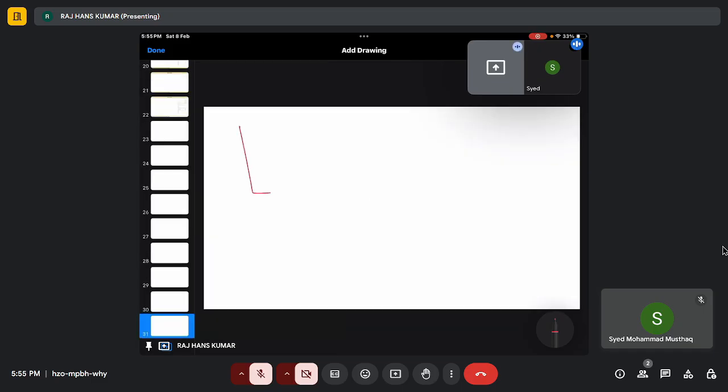Now we all know about uphill diffusion and downhill diffusion. So now, this is my G versus x curve. If I have two compositions here, xa1 and xa2, what I'm going to do is bond these two compositions. So they will arrive at a minimum composition xa0, right? So here the composition will get xa0. Then when you heat it, the atoms start to diffuse from here to here.